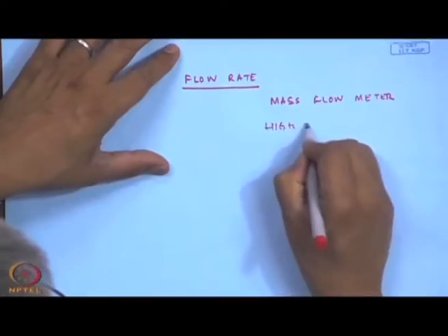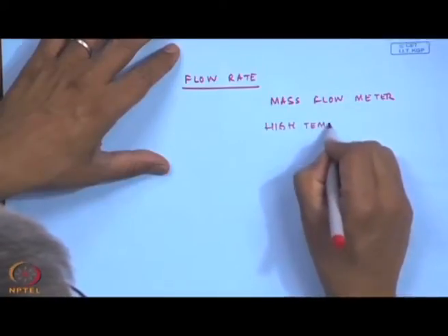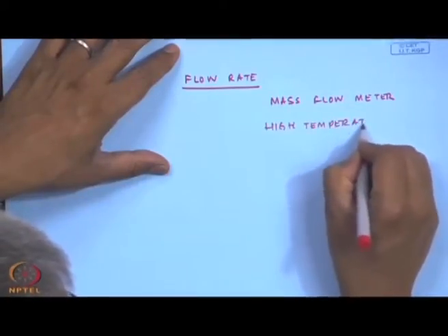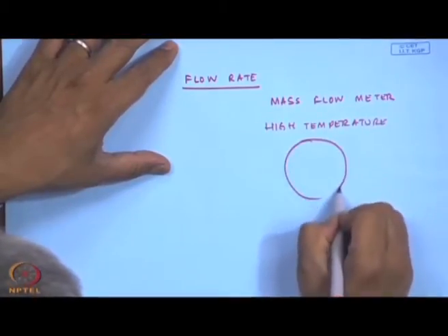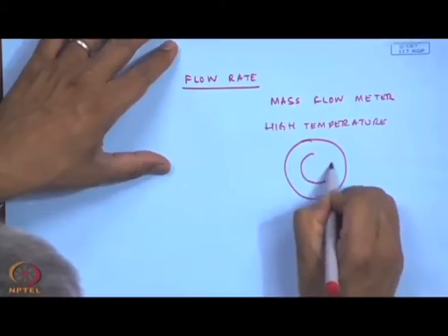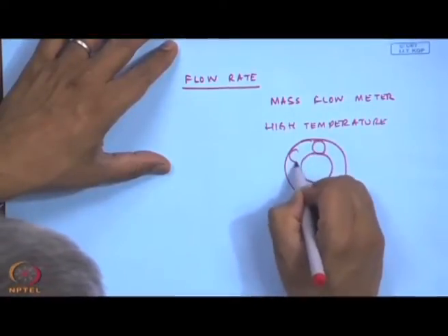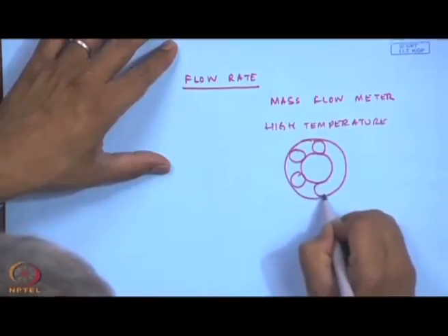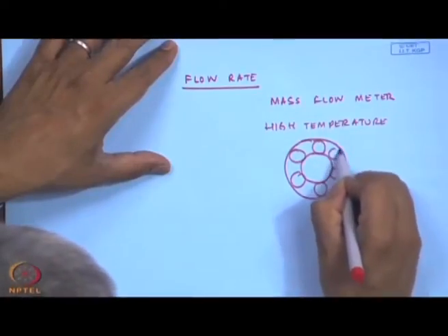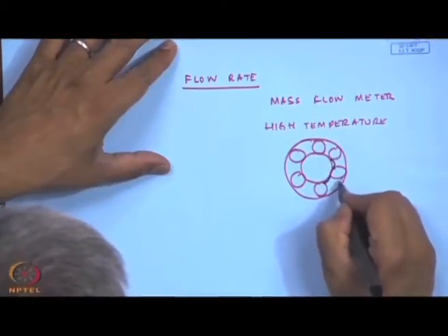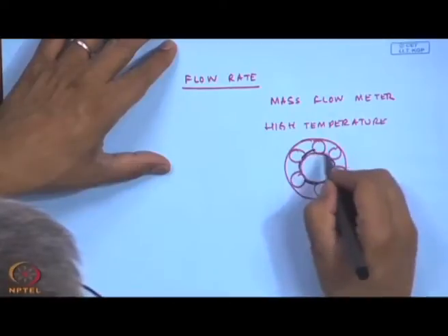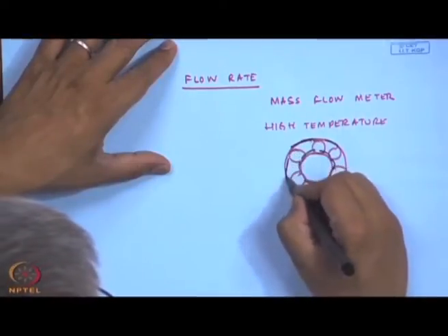How do the bearings go bad? Because of high temperature. Some of these rotors of the compressors are supported at the ends by anti-friction bearings, and these anti-friction bearings have a layer of lubricant. Okay.